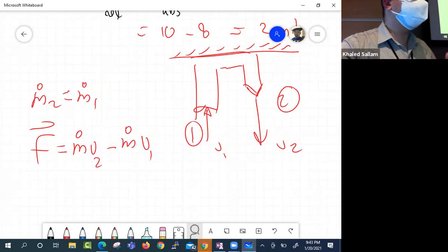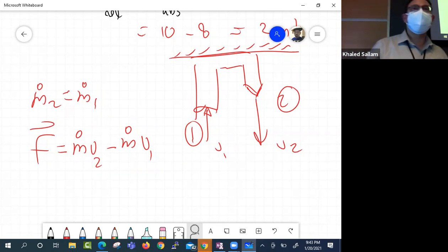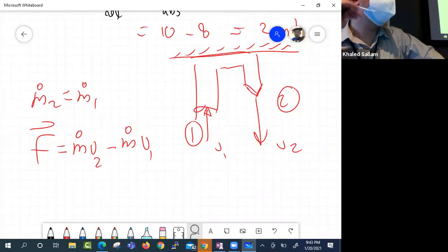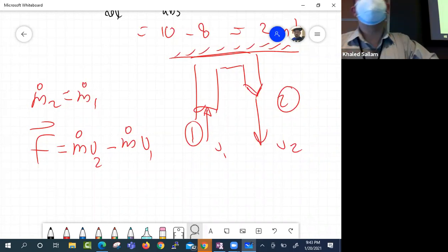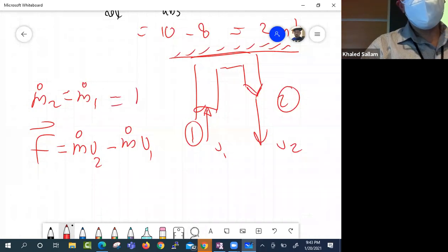Yeah, because in most engineering applications, we build things for steady state. We don't build pumps and compressors that will explode in a few minutes. You wish that everything that comes in will have to leave. Otherwise, if it doesn't leave, something is being stored and this thing will blow up. So most applications are steady state. So for steady state, m dot in equals m dot out. Unless you are working on a nuclear reactor study where you are trying to duplicate the accident that happened, maybe at that point things were coming in and not leaving, and that's why the explosion happened like 3 minutes later. So most of the time m dot 2 equals m dot 1 equals m dot.